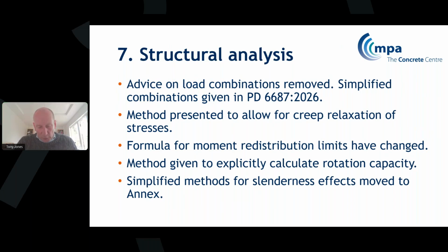The new code also presents a method to allow for creep relaxation of stresses. It'll be interesting to see how this is used by industry. So, if you consider, say, a settlement, then you get a set of forces in your structure, but because of the nature of concrete, it will creep and those will relax. So I think it'll probably have very specific uses, but it's there.